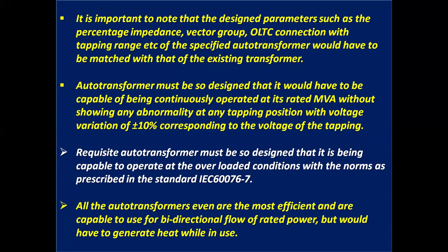Autotransformer must be so designed that it is capable of being continuously operated at its rated MVA without showing any abnormality at any tapping position with voltage variation of plus minus 10% corresponding to the voltage of the tapping.